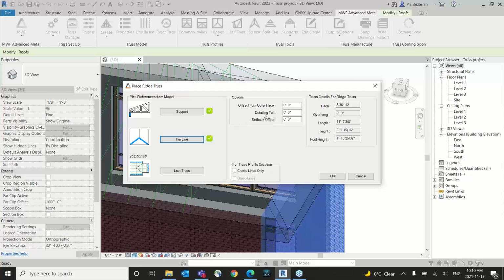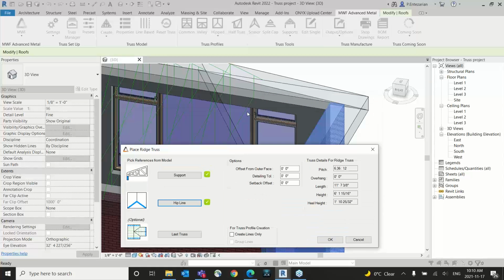We will see that when the envelope is generated, but these envelopes are the center line of the truss. So if we are having any connections, those connections cannot get placed at the point, and we need a detailing tolerance for the member to get generated.